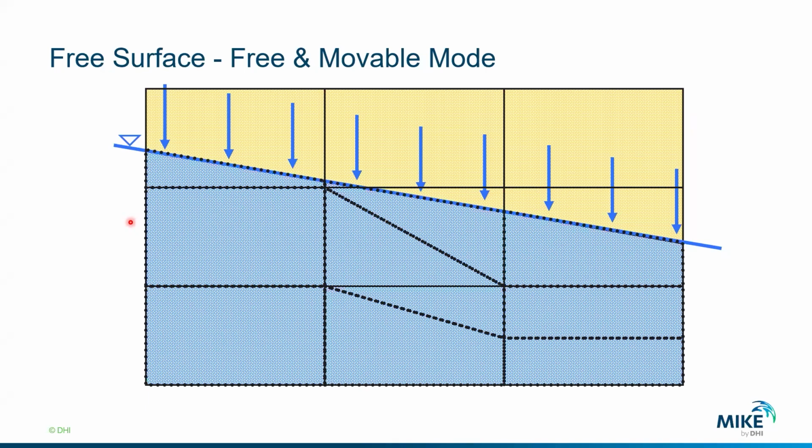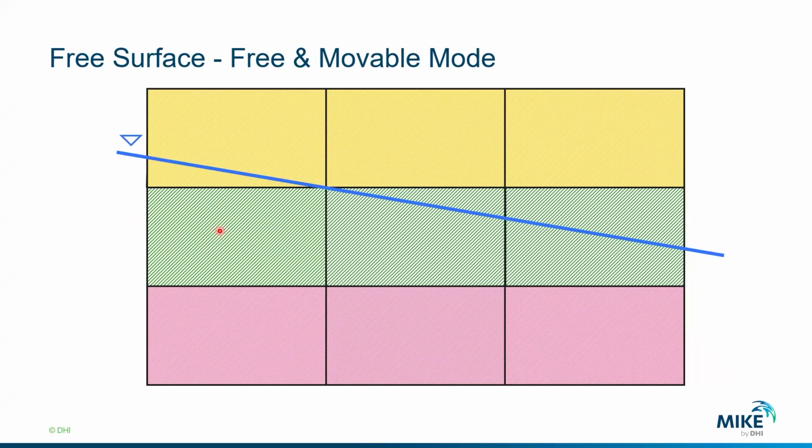So the location with a 0 pressure surface, which means if you have a drawdown because you are pumping the system, you will see that your model will collapse. If you inject water or you recharge the system, your water table will rise. Therefore, your system will also extend your domain. So this has obviously some consequences, and the direct consequence is on the parameters.